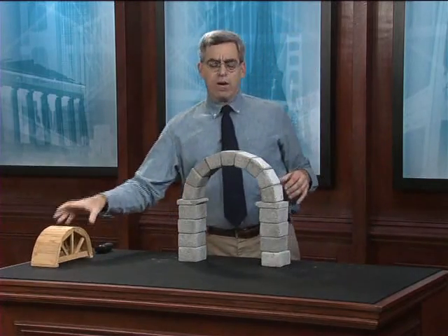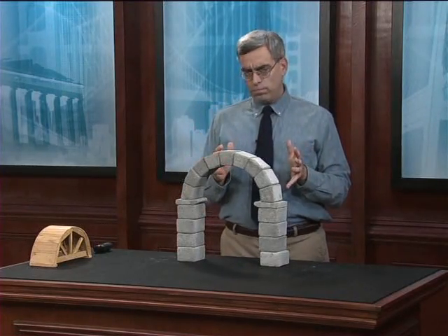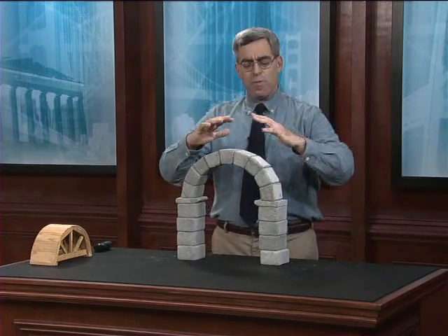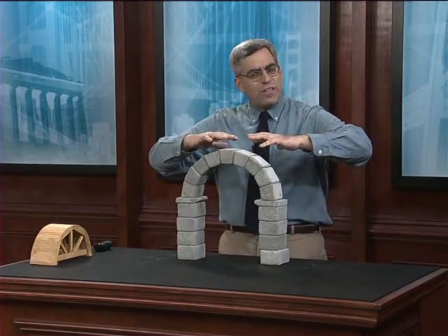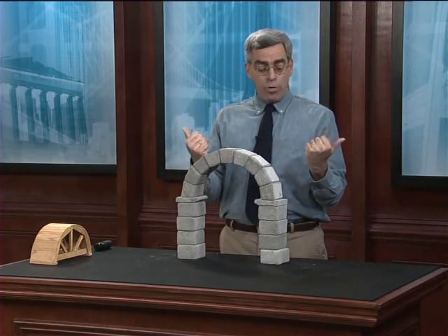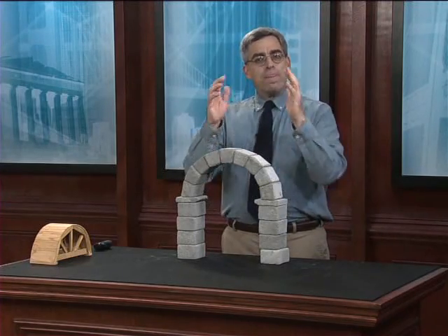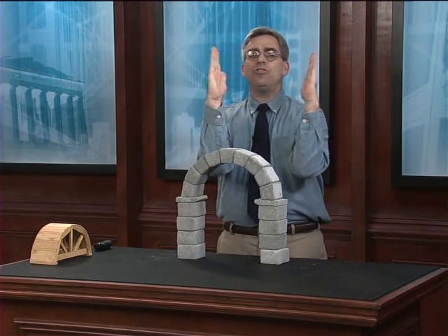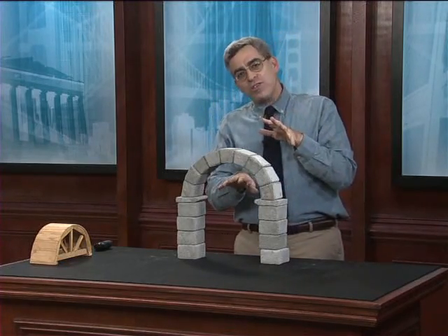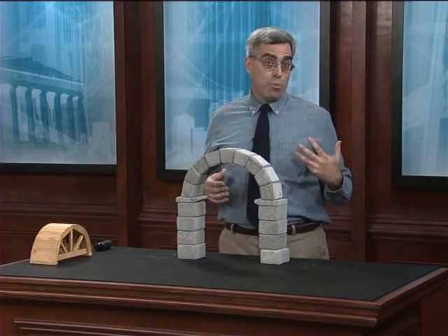What's interesting here is that the arch is standing up. It's stable. But the difficulty I had in pulling out the centering resulted from the fact that the arch is already starting to sag in the middle. The ends are trying to push outward, as they always do, but because now they're standing on tall columns, the lateral thrust of the arch is actually tending to tip the columns outward slightly. That causes the arch to flatten, and that's the reason there was less space between the arch and the centering, and it was more difficult for me to pull it out.